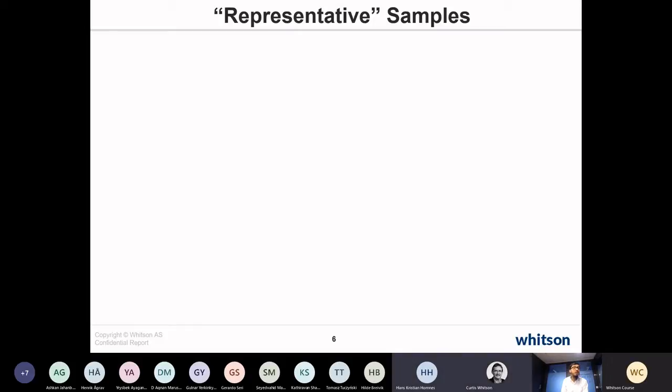So you're saying you don't think MEG is affecting the vapor-liquid equilibrium of gas oil? I don't think so, since we recommend using MEG as a back pressure medium. But I'm not 100% sure regarding the water sampling. For the oil and gas sampling it has no effect. Yeah, it's definitely a topic we'll come back to visit. I think if there would have been a big effect of MEG on vapor-liquid equilibrium of the gas oil system, I would have at least heard about it. So I suspect you're right on that.